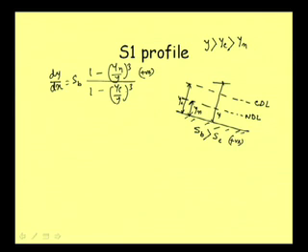In the denominator also yc by y is a fraction, and its cube will again be less than 1, and 1 minus something less than 1 will become positive. SB is also positive. So that way we are getting that dy/dx is positive. Well, that means it is a rising profile.